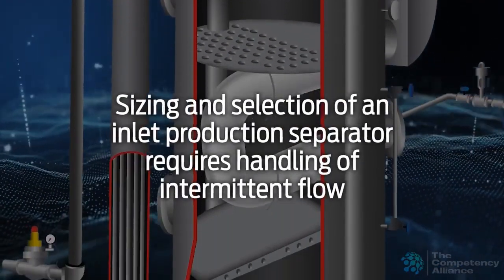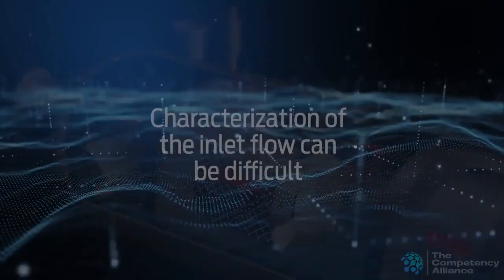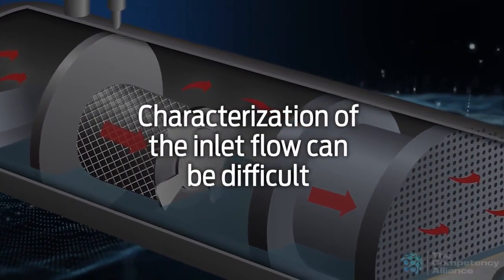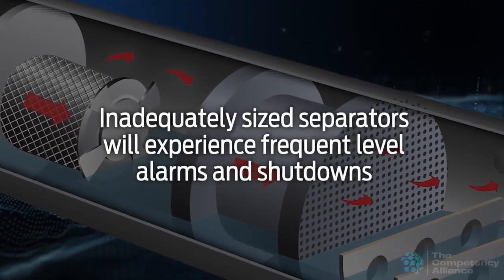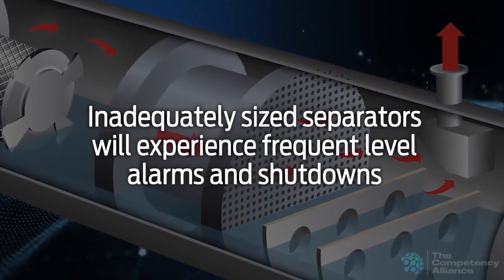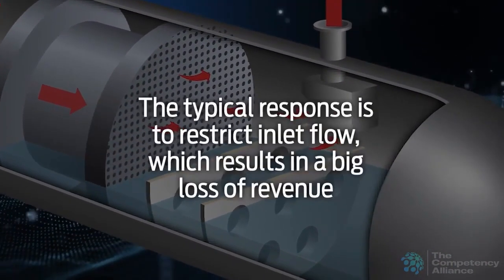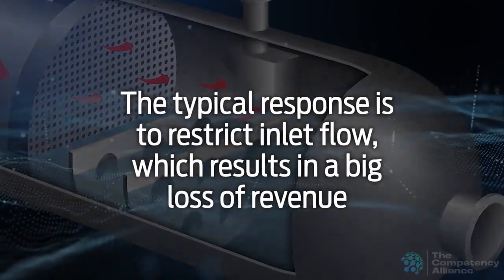Sizing and selection of an inlet production separator requires handling of intermittent flow. The difficulty is in characterization of the inlet flow, that is, gas and liquid flow rates as a function of time, which needs an evaluation of the upstream supply. Inadequately sized separators will experience frequent level alarms and shutdowns, and also, by necessity, pass the surges downstream, leading to unstable operation. The typical response is to restrict inlet flow, which costs a big loss of revenue.